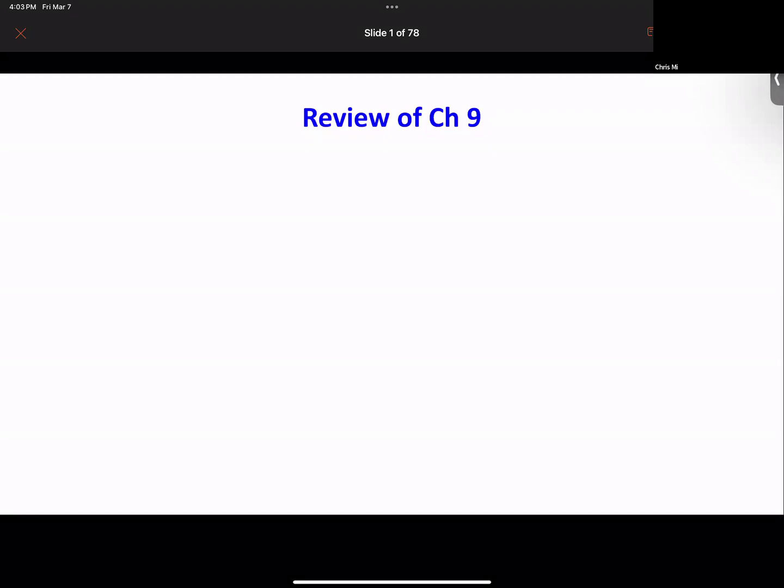So then we move on saying, well, for these differential amplifiers, what happens is that if you have a mismatch in your circuits, whether it's gain mismatch, transistor mismatch, or resistor mismatch, your output is going to be different, even though the input is common mode. So now we have to find out what is the common mode gain.